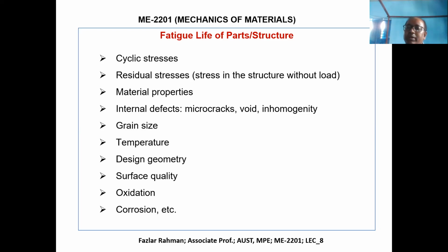Okay, so he unloaded some goods in Alaska and stayed for 15 days. So for the whole 15 days the ship will be shrunk. Then he loaded the ship and came back to China again. Back in the warmer temperature, all the material will again expand. A ship is designed for 30 years or 15 years. Why don't we design for 90 or 100 years? If we do that, maintenance cost will be extremely high. So during design, I have to think about how many times that ship will shrink and how many times it will expand.